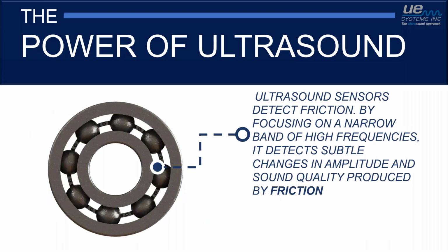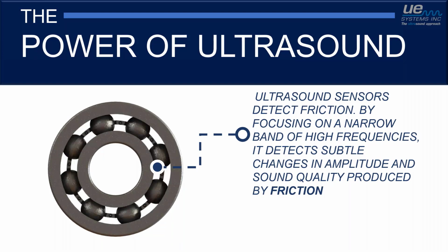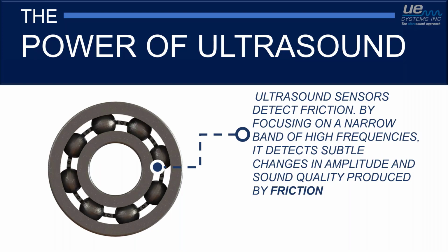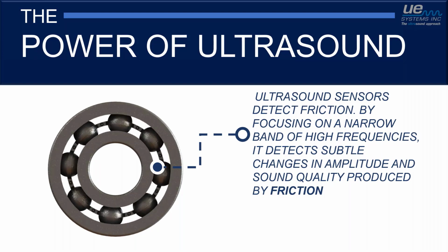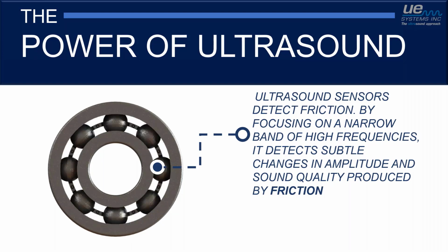And really the fundamentals around it is we're looking at a very high band of frequency. So we're looking at 22 kilohertz and above. In this case, in bearings, we're up in the 30 kilohertz range. So obviously our ears can't hear it, right? We're not going to walk by a bearing, if you walk by a bearing, and most of us have done that.